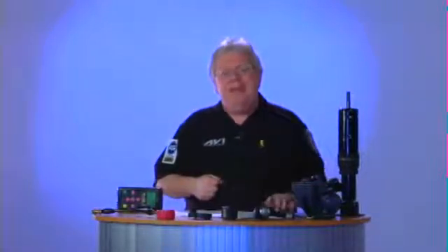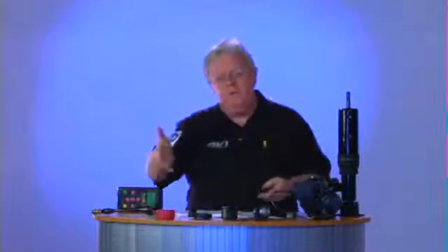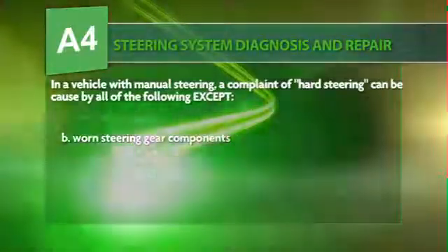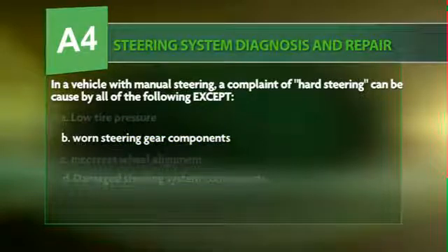So the correct answer to this question, the wrong answer, they're looking for the word "except" there, would be B, because we know we've talked about incorrect wheel alignment and damaged steering wheel components and low tire pressure could all be causes of hard steering. The one that can't cause hard steering, or usually won't, would be worn steering gear components. Let's go on to our next question.